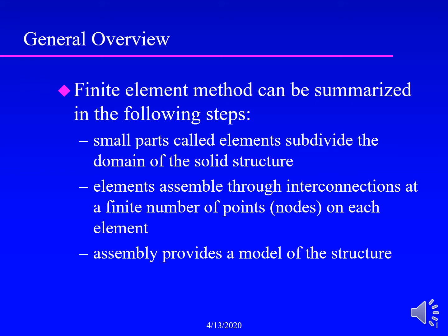where we require to solve these differential equations is divided into small parts called elements, subdividing the domain of the solid. The elements are assembled through interconnections at a finite number of points, nodes, on each element. So when this whole structure is divided into different elements, the elements are connected at the nodes, and the assembly provides a model of the structure.